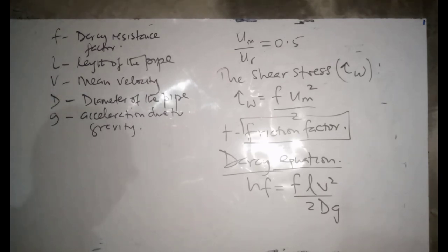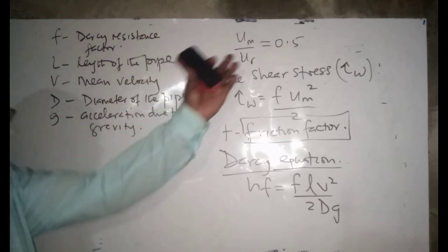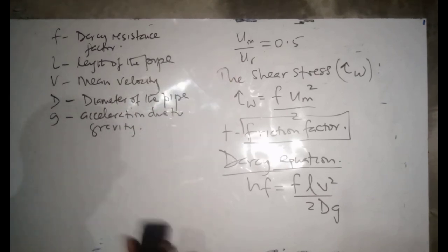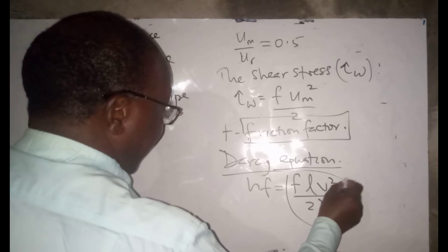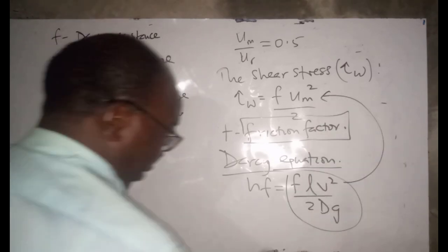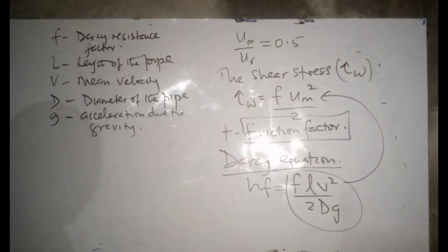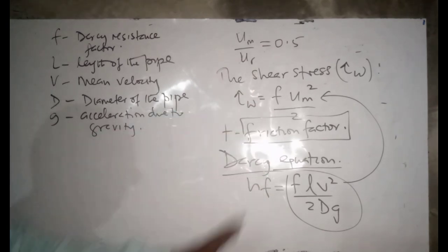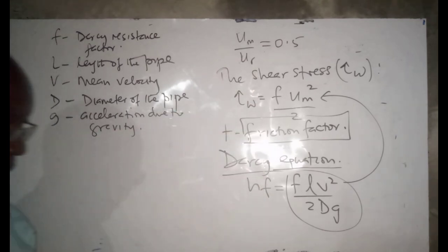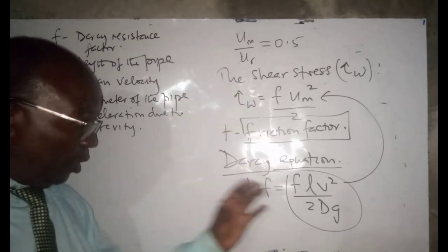So even in terms of just the velocity in the axis of a tube, if you are looking at that and not looking at the annulus, then you can just use that ratio and you'll not be very far off from what you expected. So this friction factor, if we plug it into this particular equation, you can see that the friction factor is inversely proportional to the diameter of that particular pipe, and of course is directly proportional to the length.